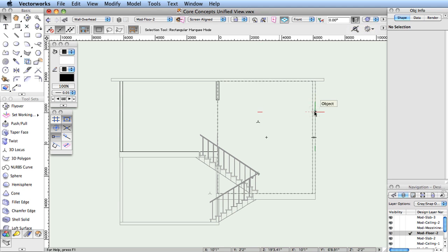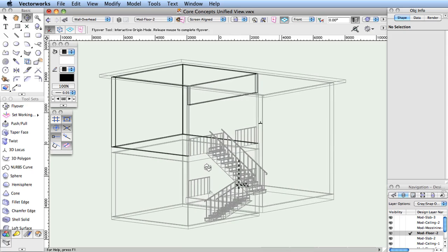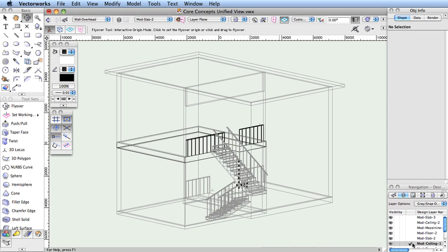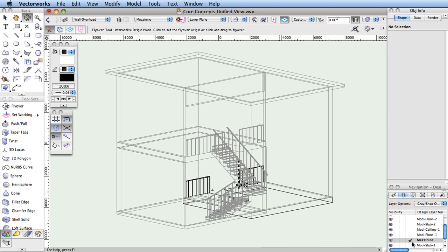While in Unified View, Vectorworks aligns all visible layers in the drawing with the active layer as you navigate in the document window, and displays them using the active layer's scale, lighting options, render mode, and RenderWorks background. The Unified View also provides a unified coordinate system. The z-coordinates of all objects are expressed relative to the active layer plane. Other layers are above or below the active layer, depending on their elevation's relationship to the active layer.